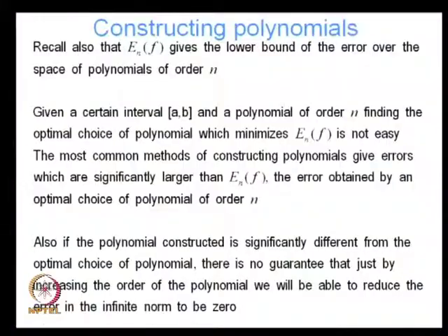That is very important, and that is why the finite element method works. The finite element method has something known as the best approximation property. It is in some sense an optimal choice of approximation. The polynomials that we use in the finite element method are the optimal polynomials in a certain sense. So that is why choosing any higher order polynomial is not going to give me a substantial reduction in error.